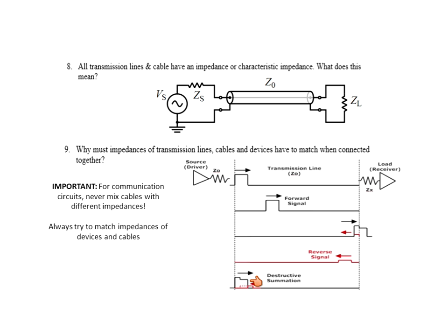So, why must the impedances match? If you have a mismatch, you will not have proper power transfer. It will cause reflections on the line. Typically, you have a mismatch on both ends. The signal will just bounce around between the transmitter and receiver and cause standing waves. That's more than we need to talk about here.